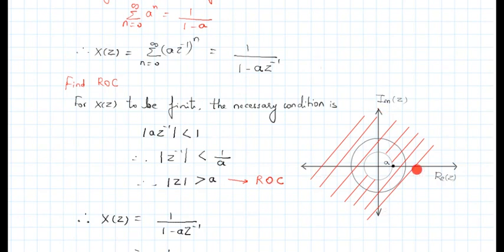So we know the z-plane. Now let us come back to the z-plane that we discussed at the start. The z-plane comprises the real part of z and the imaginary part of z. Let me say this is my unit circle, and a is a value which is something less than 1. Then I get one more circle whose radius is a. Now where is my ROC existing? ROC should exist outside a. Correct? So you could see here.